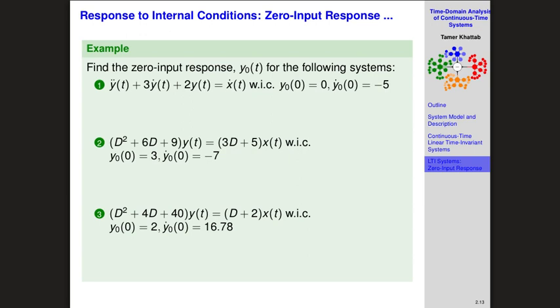So if I know the suspension system's natural behavior, the case when you analyze the suspension system without any input, generally has a behavior which is exponentially decaying, then this means that the suspension system is going to hit this bump, and then the car is going to move a little bit up and down on the suspension and then continue. If I notice in the initial analysis with zero input that it has some sinusoidal, then after hitting the bump, the car is going to do this, but with a decaying sinusoid, right?